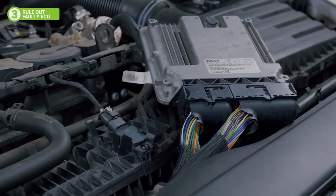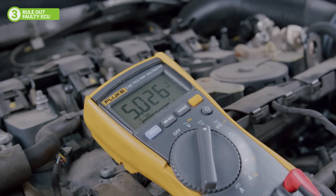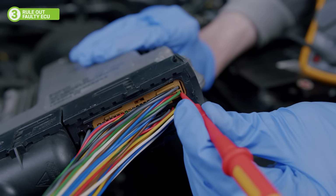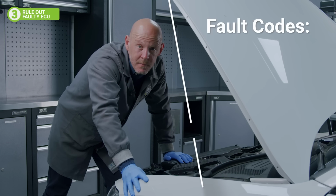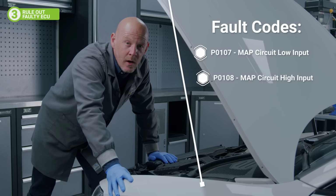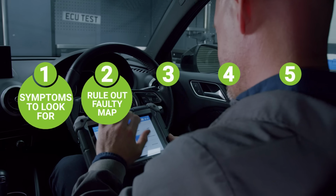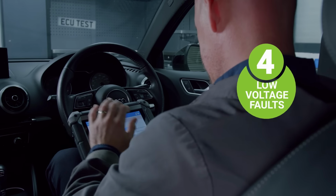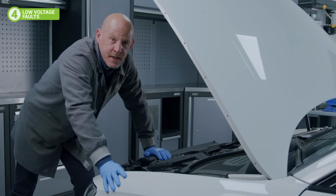If you've verified that the engine control module is outputting the correct voltages, then we need to conduct further investigations depending on whether the readings at the sensor or the ECU signal wire connection are higher or lower than the expected ranges. Two of the most common symptoms of a MAP sensor circuit malfunction are the codes P0107 and P0108. Let's start with the first of these annoying codes. P0107 means MAP sensor circuit voltage low.